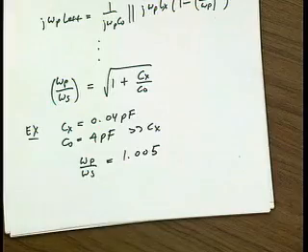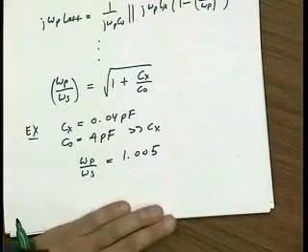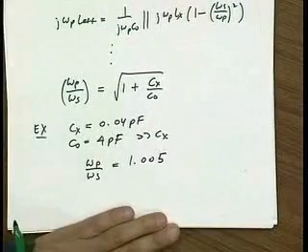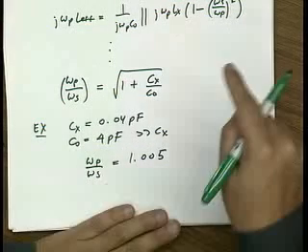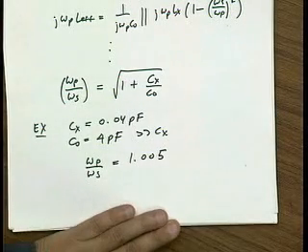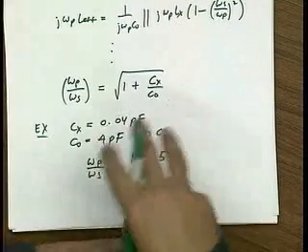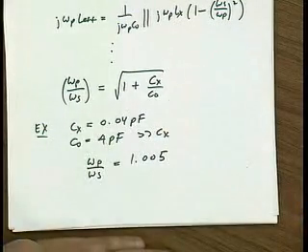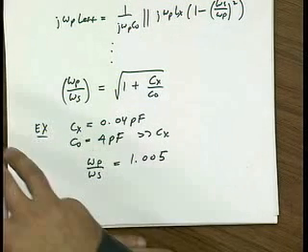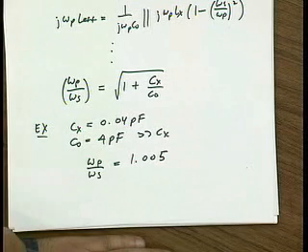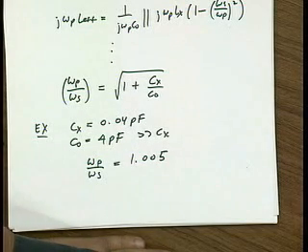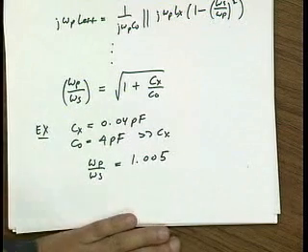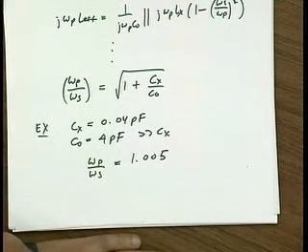So if you buy a crystal and it says that it'll resonate at 1 megahertz, they're actually on the can, it'll tell you what external capacitance you should connect for it to resonate at that 1 megahertz. So the crystal manufacturer already is assuming that you're going to put some C in shunt. And so when you design your circuits, you should make sure that your capacitance is equal to what they're telling you to put. And usually the value of capacitance is pretty reasonable. It's something that you can easily achieve. It's not femtofarads or attofarads. It's actually on the order of hundreds of femtofarads to picofarads. And you put that capacitance in parallel, and you will hit that resonance frequency dead on. Okay?